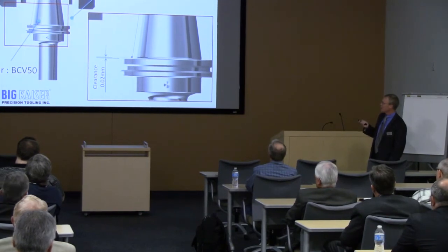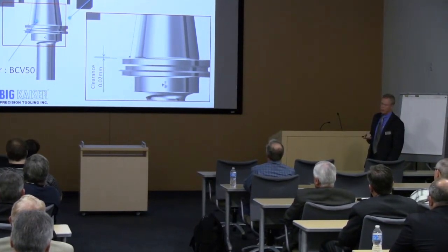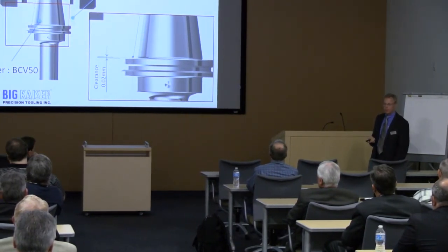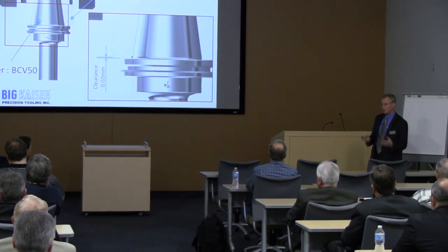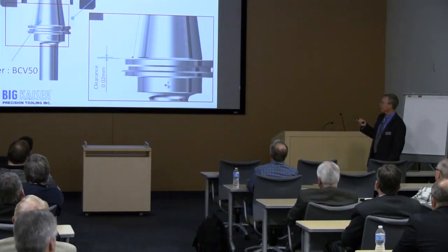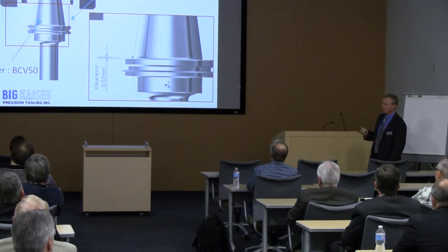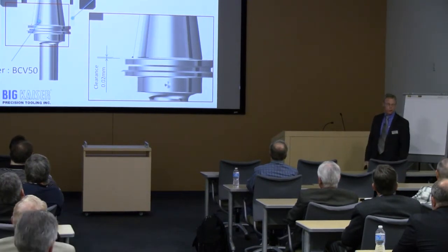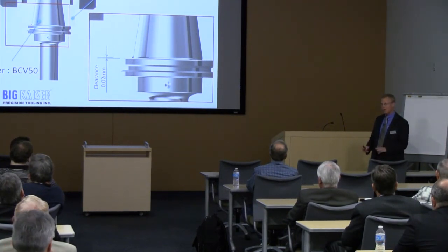Now, when I clamp this retention system with a 50 taper, it's about 4,000 pounds, a lot of pressure. Every machine throughout the ages has always had an elastic nature. When I clamp a tool, it's going to pull itself back in a little further. These spindle bearings and everything have an elastic limit to them. They move under this pressure. That's a known, repeatable amount. Every machine does it.